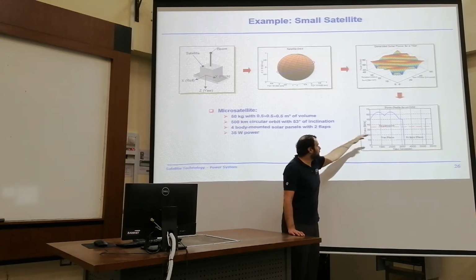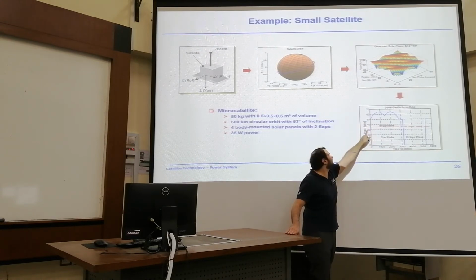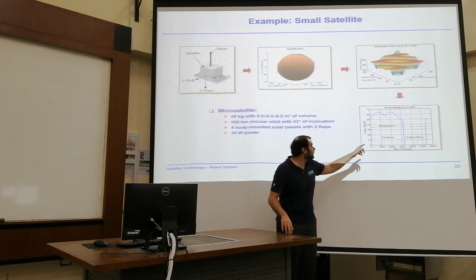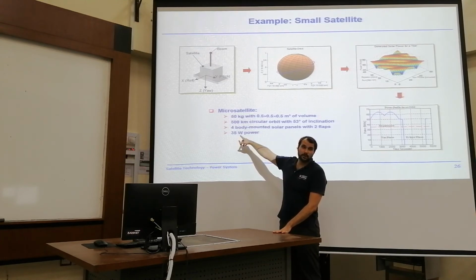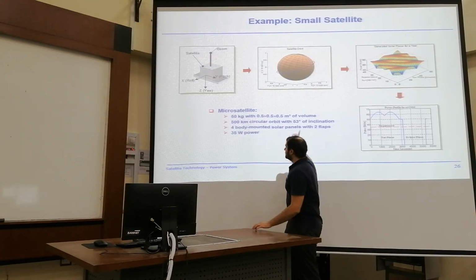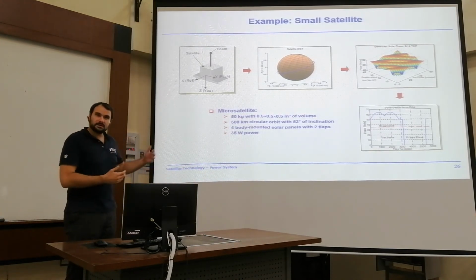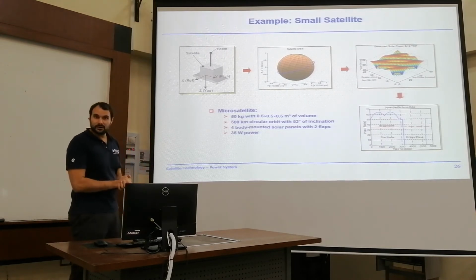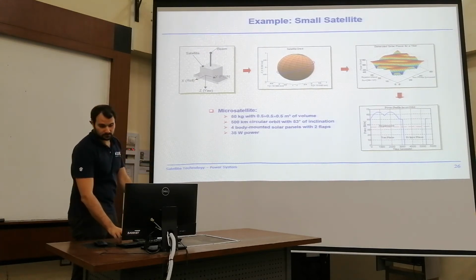And just to account for this eclipse phase, we need to install a much higher power on board of our satellite, more than 60, around 65 watts peak power in terms of solar panels. Keep in mind, we only wanted 35 watts of average power. This is going to be part of one of our exercises later, to have some nice and neat calculations and get more into detail, so that you at least did it once for yourself and see how much overhead you often need to install.